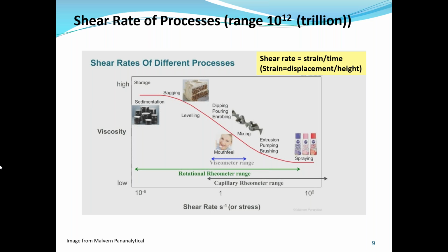And then in terms of gap positioning, height or force, it depends on the properties. The reason I say that is that in the gapping of that butter at 5 degrees, you can maybe get some fracturing of that butter to occur. And so you may want to see if you want to condition that butter, maybe take it up to a higher temperature or gap it at 25 degrees, and then cool the plate down to 5 degrees.